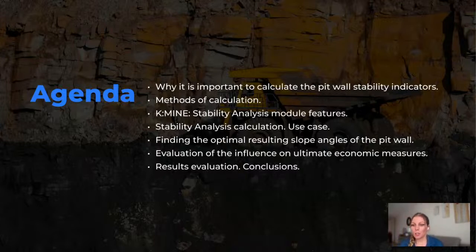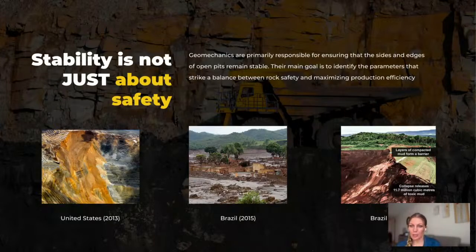When mining companies use an open method, it's super important to make sure that the rocks don't collapse at the edges and the sides of the pit. Basically, the angle of the slope is what determines how stable it is. If the slope angle is too steep in the construction plan, it can lead to a sudden collapse of the pit walls or ledges. But if the angle is too low and the pit is really deep, then it can be too expensive to mine.